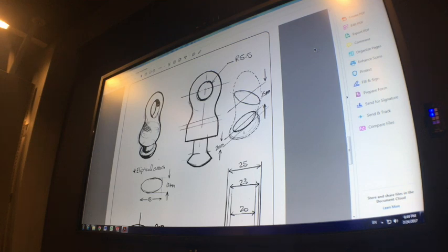It's not really a shape that's extruded straight up, and it's not revolved. We do use a revolve feature in this shape to create this bottom section. So this bottom section, if you have a look again at that 3D, that part looks like it's 360 degrees the same kind of profile, whereas the top section has that sort of twist to it, where you can see here where there's two ellipses at a 90-degree angle.